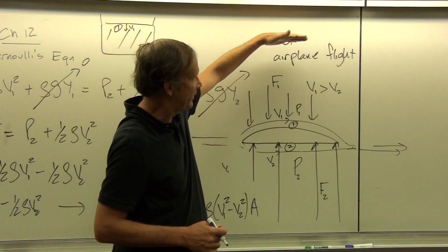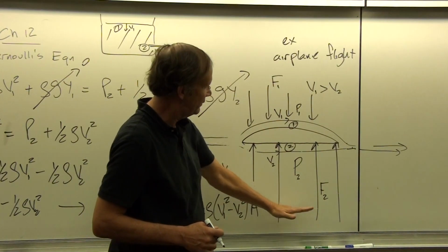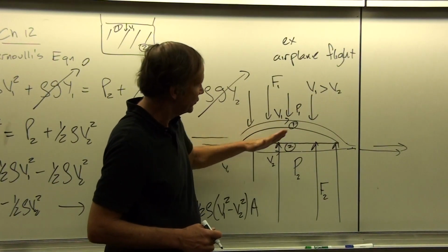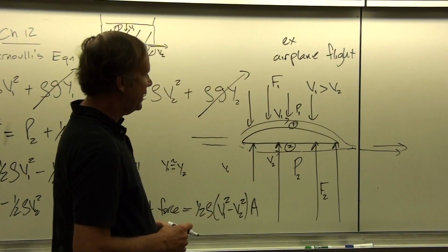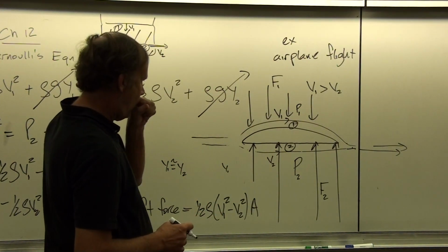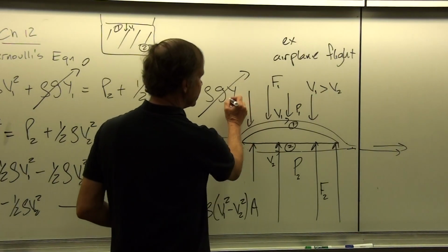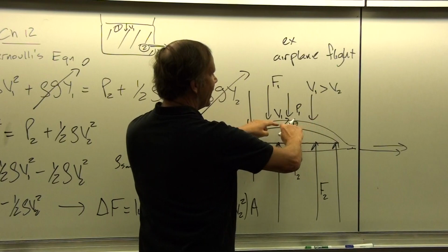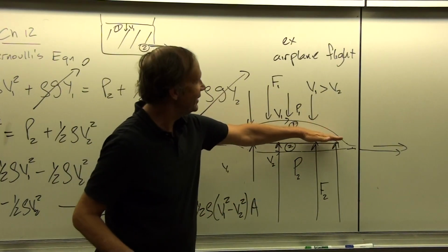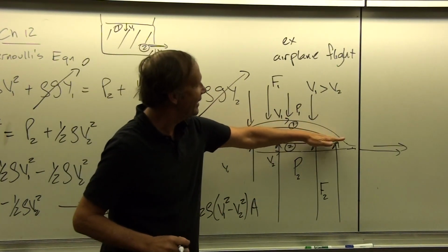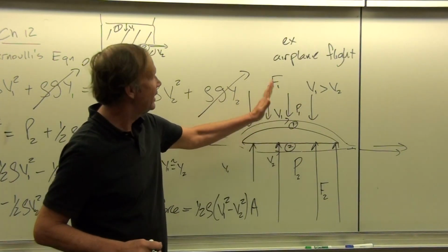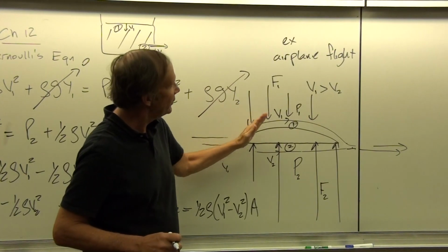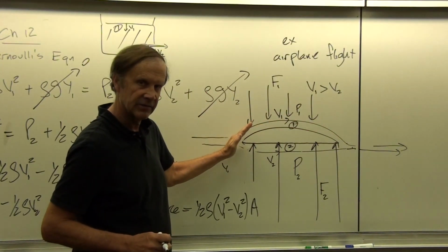So say if you had the sun shining directly from above, it'd be a cross-sectional area of this wing, which would be essentially the area of the shadow of the wing. Because remember, the pressure forces here come in perpendicular to the surface, but the sideways components cancel, unless you think in terms of the effective wing area as being the cross-section. Then it's only the vertical component that's going to contribute, and you already know that the horizontal components are going to cancel out.